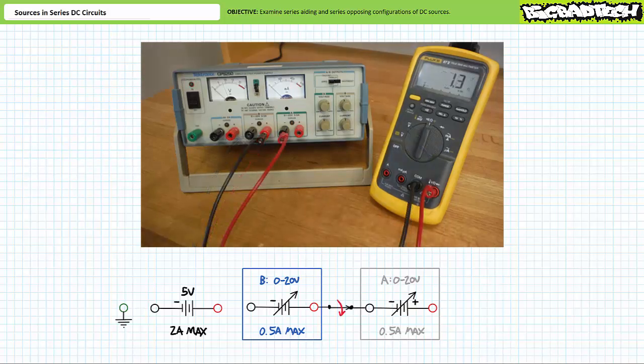If a user was to change the selector switch in the upper right-hand corner to series, the source closes a switch between the adjustable A and B source. You will note the closed switch stacks A on top of B, such that source B's positive terminal and source A's negative terminal are electrically connected in a series aiding relationship. With a power supply in series mode, an ohm meter demonstrates that these 2 points are now connected.